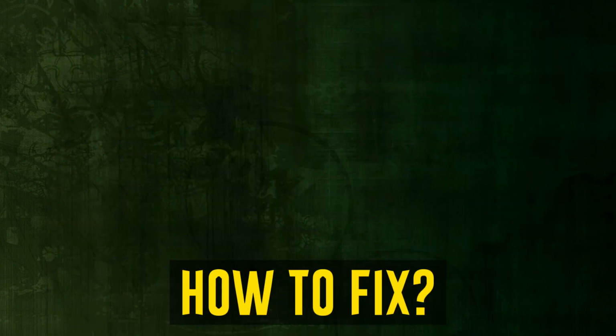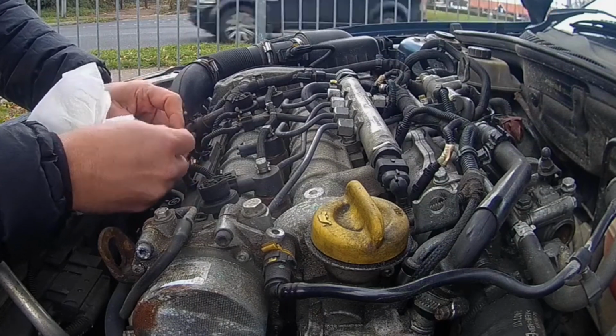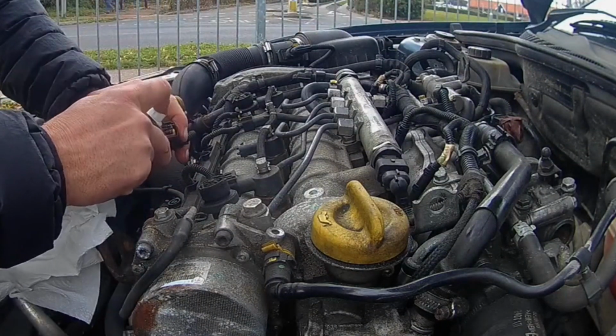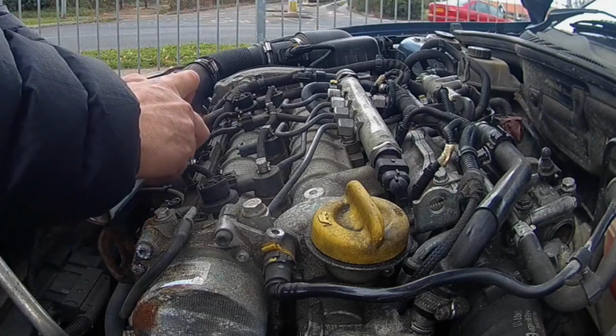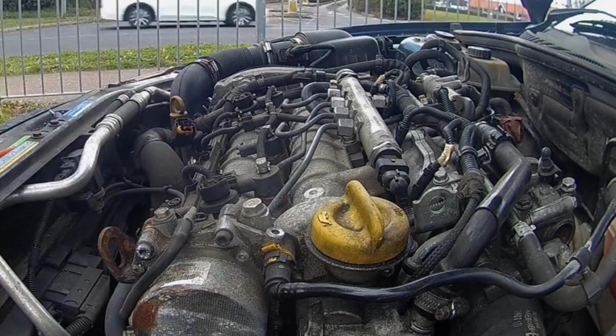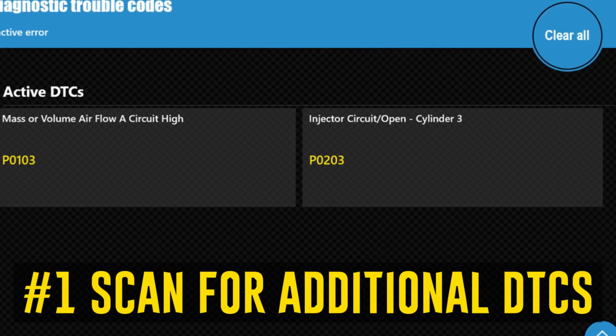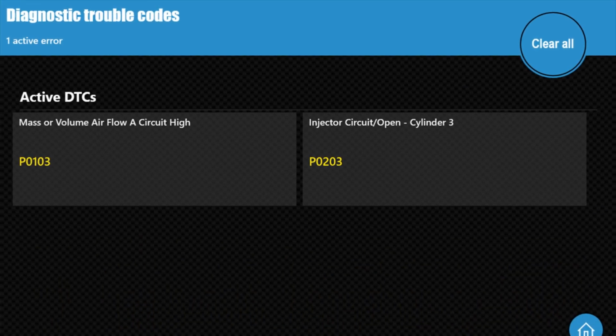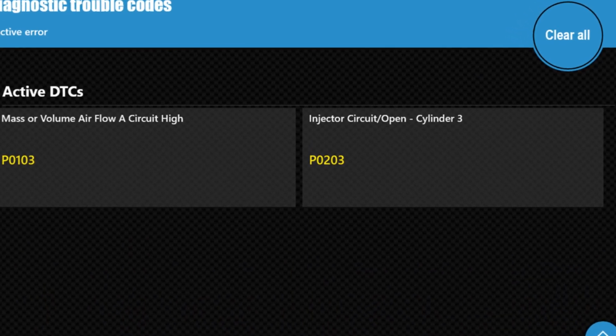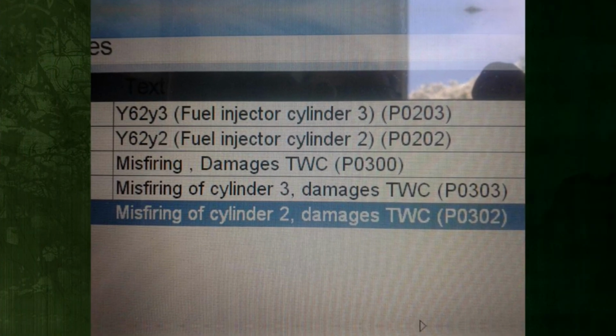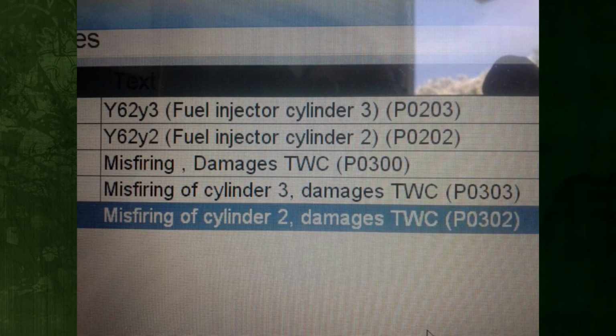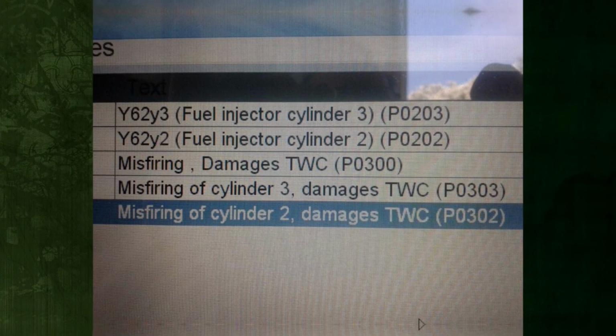How to fix. You can use the following steps to help diagnose this fault code on your vehicle. As usual, before attempting any such repairs, make sure to consult factory-specific service literature. Scan for additional codes. Using an OBD-II scan tool, one should look for additional diagnostic fault codes prior to starting the diagnostic procedure. Before moving further, any such codes that are discovered need to be properly diagnosed.